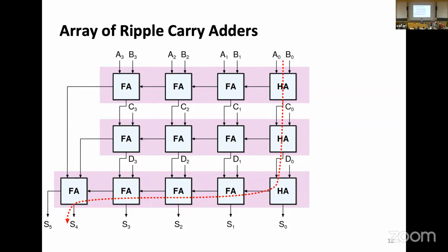Now, we are trying to add four different numbers. And we realized that by organizing these ripple carry adders, 1, 2, 3 of them, we can actually accomplish this. However, this is a special case. The only reason this works is because this last adder is really slow, because it's a ripple carry adder, right? And while this guy is slowly propagating, these guys catch up.